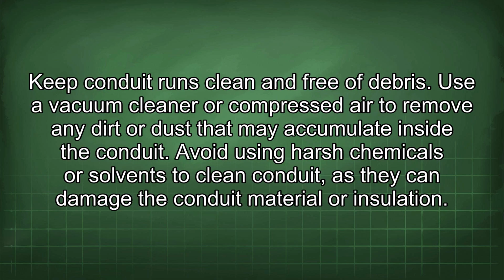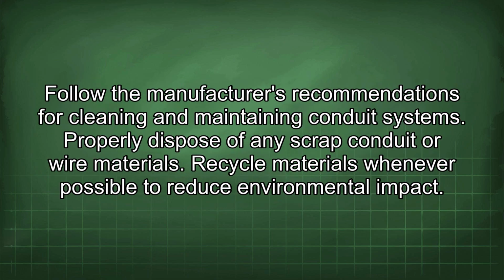Keep conduit runs clean and free of debris. Use a vacuum cleaner or compressed air to remove any dirt or dust that may accumulate inside the conduit. Avoid using harsh chemicals or solvents to clean conduit, as they can damage the conduit material or insulation. Follow the manufacturer's recommendations for cleaning and maintaining conduit systems.